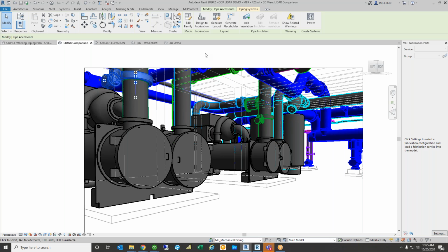So if it's a class 125 or a class 150 valve, then it's going to have the flange patterns and the thicknesses of the body assembly and all those things, so that your spacing between your flanges for this valve to sit are actually correct.